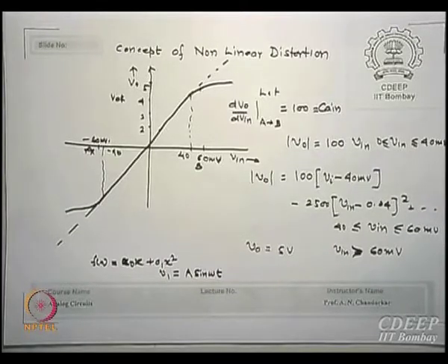So these are called harmonics. Omega is called the fundamental; any number proportional to this omega, 2 omega, 3 omega, these are called harmonics. But whenever harmonics are present, the output will also show you those corresponding frequency components. V0 will also have components of 2 omega t, 3 omega t, apart from omega t.